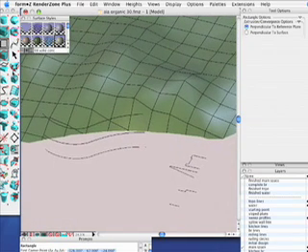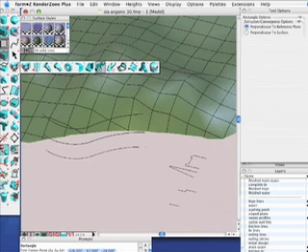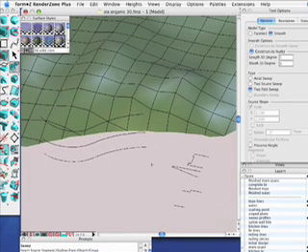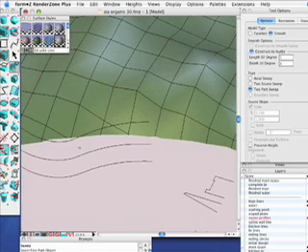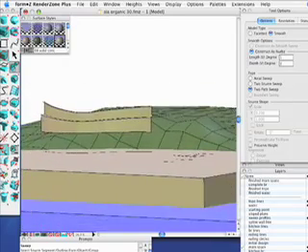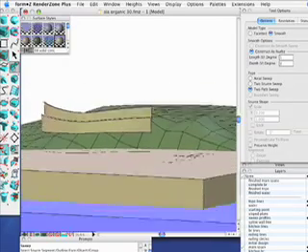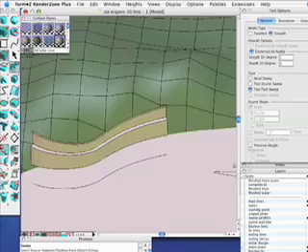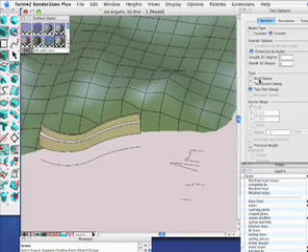In this particular case, I'll use these profiles. So let me go to my sweep tool, and I'm going to do a 2-path sweep. This is taking one profile line and making it conform to 2 paths at once. So I'll pick those 2 paths. So you can see how that profile has been stretched and rotated to match the position of those 2 path lines.